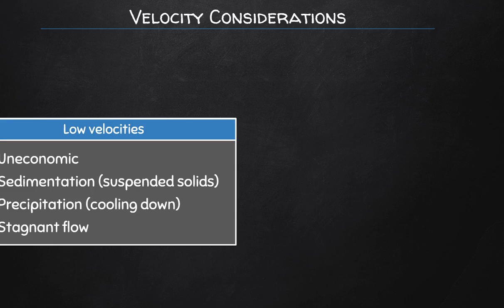So this resulted in there being a much higher temperature inside the reactor rather than it having good mixing. Stagnation caused pockets of cold pulp to be measured, and so the process controllers thought that the reactor was operating below 80 degrees when in fact they had already heated the output to 95 degrees, which is unsafe.